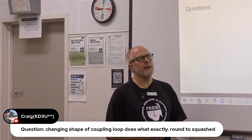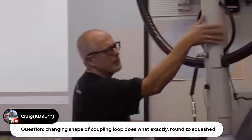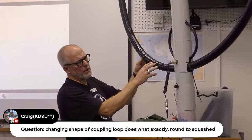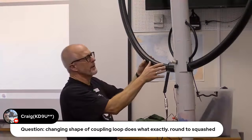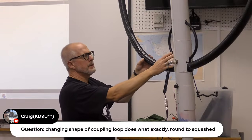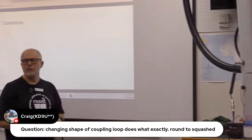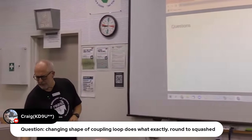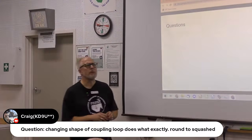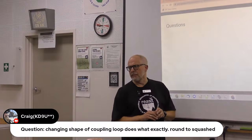Okay, that would affect the coupling efficiency because the surface area of your coupling loop is intersecting with the radiation pattern effectively. So I'm not sure it would cause the efficiency to go down, but your radiation pattern may be affected. Not sure about that. Can I make a comment there, Justin? Yeah. Some people squash the loop in order to increase the surface area contact between the two loops to improve the efficiency. Okay. The position of the coupling loop also has an impact on the SWR or your impedance. Correct. So you can adjust it around until you get the correct impedance.